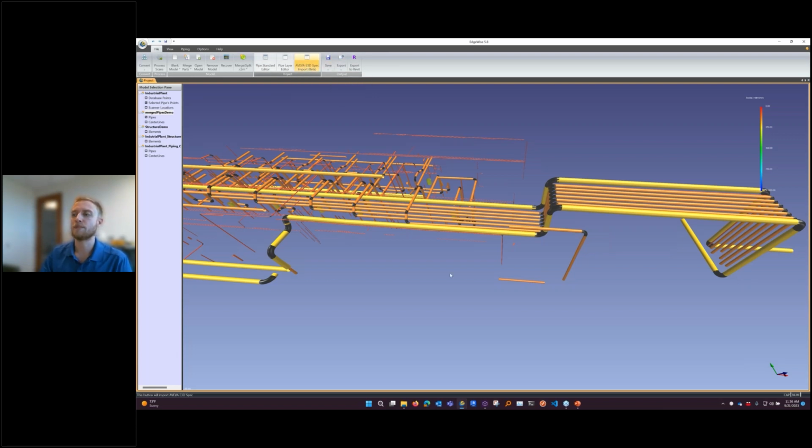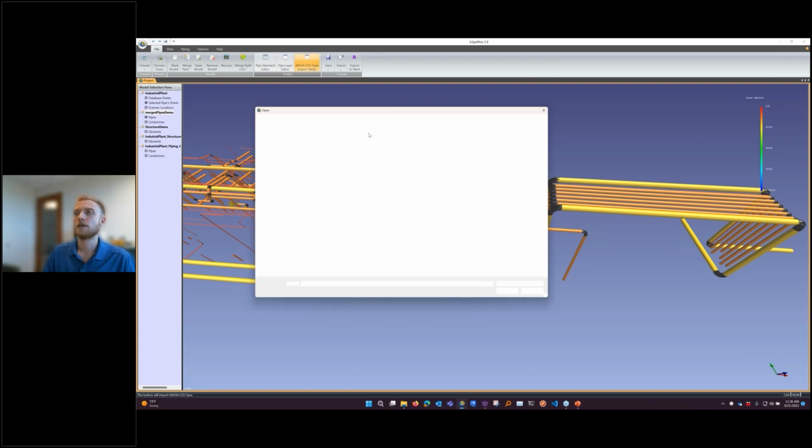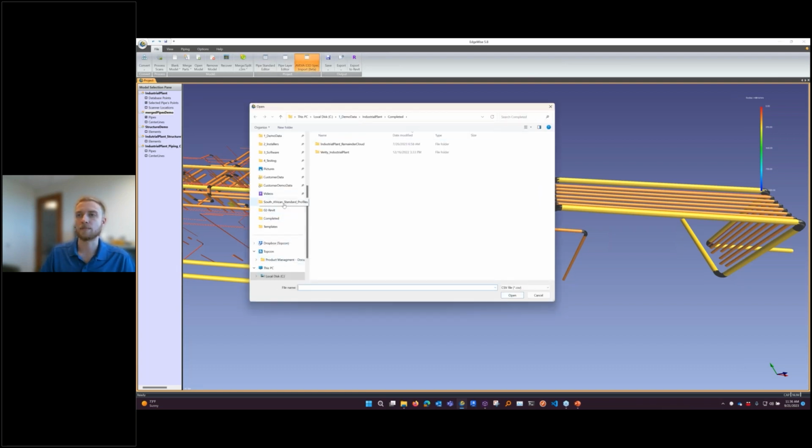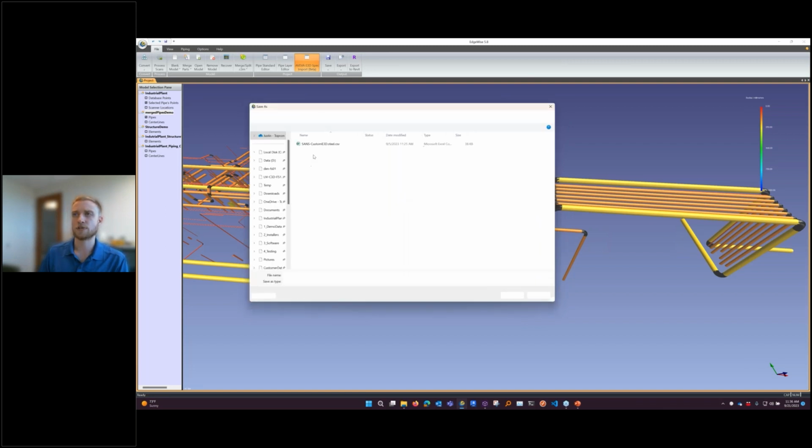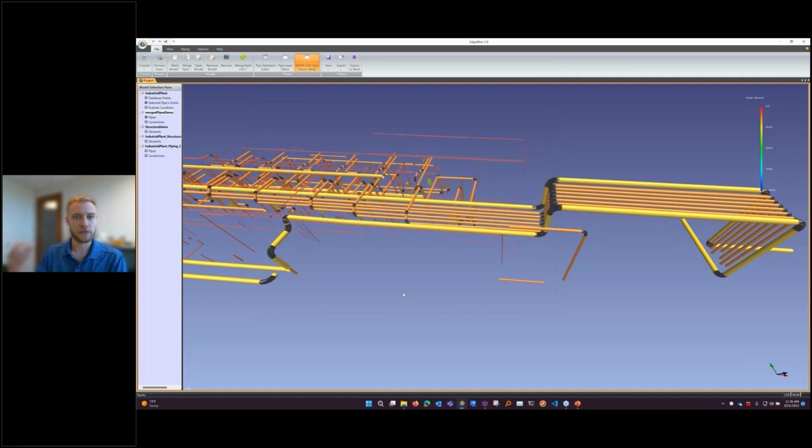So just to kind of briefly show it, I'm not going to go to Paragon and export the catalog, but you would go to Paragon, you would select the catalog you want to work with, and you would export that as CSV files. We can kind of take a look here on what that would look like. So in this case, this is just all of the catalogs from E3D. So this is just going through and exporting each of these for all the different steel that I want to work with. I can open this, and then EdgeWise will actually let me save out an EdgeWise standard. And so I could use this guy right here and save this, and then that will be an EdgeWise custom standard based off of that catalog for E3D.